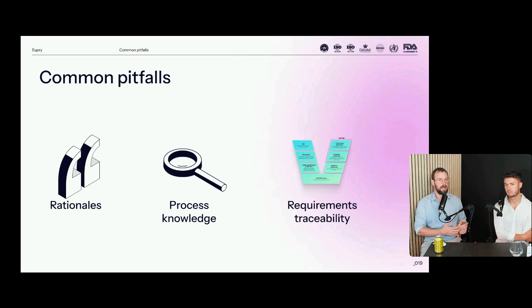The ISPE guidelines do give a concept in which, if you have symmetry in your warehouse, so basically you have a large square warehouse, well, you can divide it into smaller sections that are alike, and you can perform a quote unquote full mapping on those areas separately. Because yes, it is most likely impossible to achieve a full loaded warehouse during a mapping study. It's often not economically feasible as well. But yes, it is a great concern, and you really do need to take into account the risks associated.